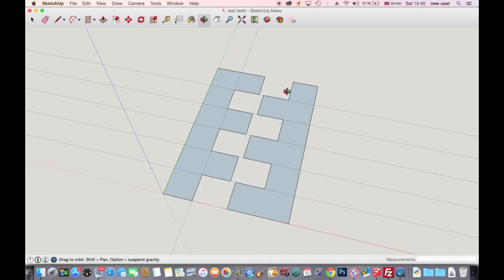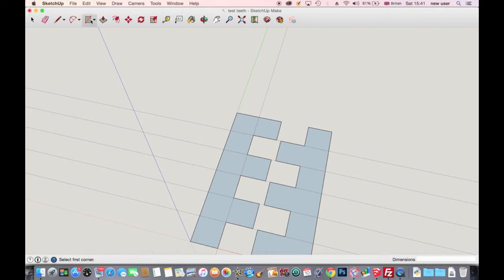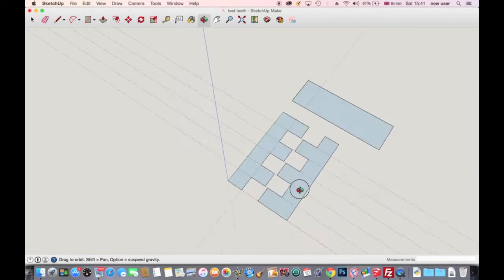It compensates for the beam width. The G-code path it creates is offset to the outer edge of the faces that you put into it. Basically, if you create just a square but without a face, that actually won't work with my program for now. What it's optimized to do is to take a drawing which is created on the zero plane, like it's a flat drawing in SketchUp.